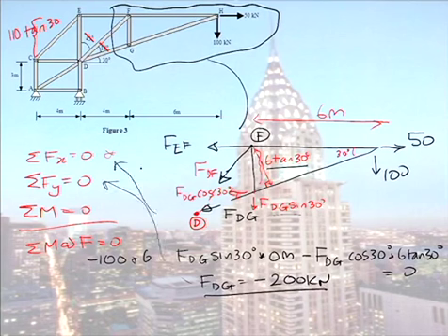Now, you could then choose to go back to your forces in the x or forces in the y direction, or you can just take moments this time at D. Taking moments at D here, can you see what force you would solve for? You would solve directly for FEF. So I will leave you to do that yourself, to finish off that problem. And all answers to past exam papers you will find online on the exam paper itself. Okay, so that is stresses under control.